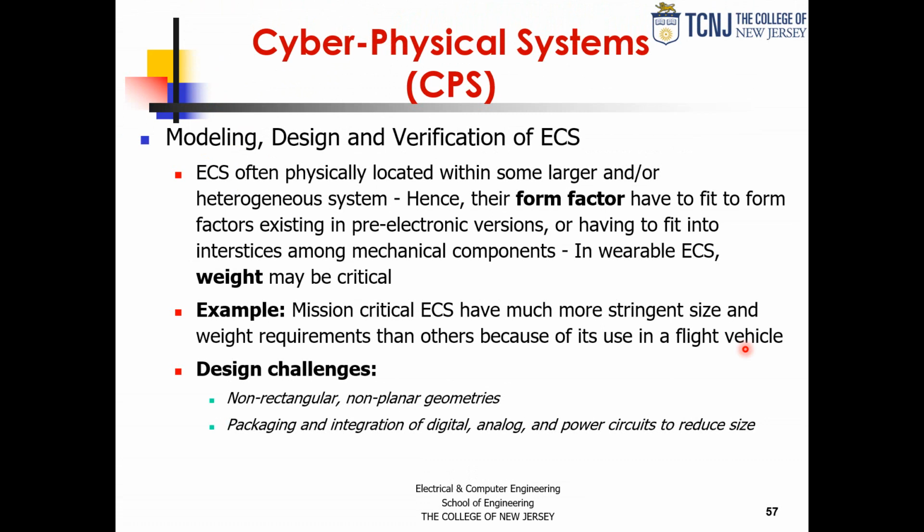So other things that it allows us to do, look at physical issues like power. You can have power budgets that are modeled based on activity of the different components. So you start getting an idea of what type of power before you have something. Of course, once you have something, and you measure the current, and you measure the voltage, and you measure the power, then you know exactly what the consumption is.